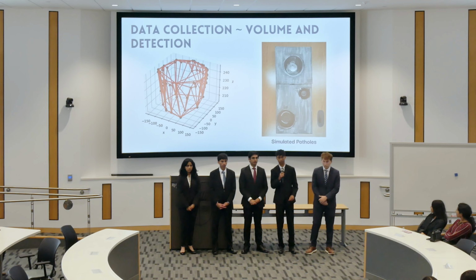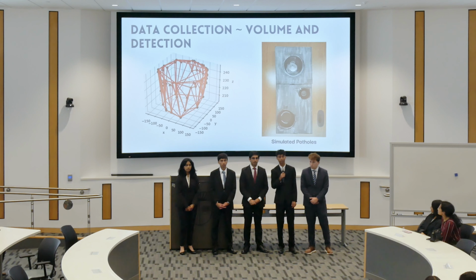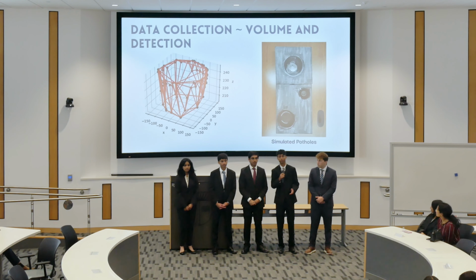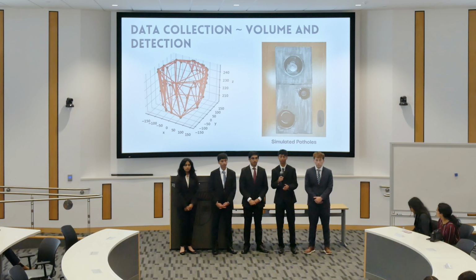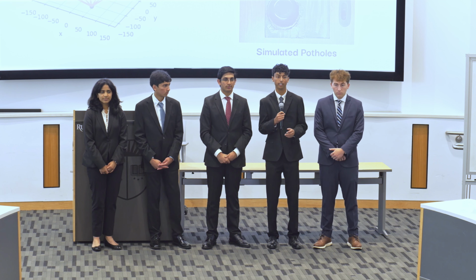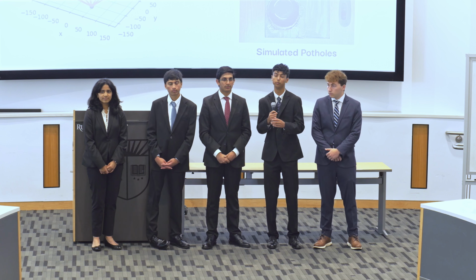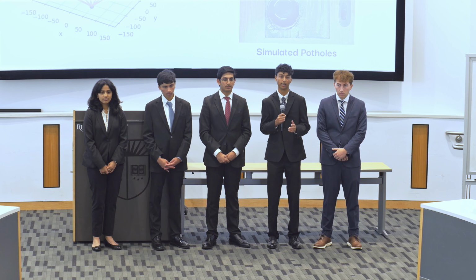For our pothole detection module, we implemented 3 algorithms: adaptive breakpoint detection, iterative endpoint fit, and gradient comparison. Adaptive breakpoint detection organizes our data into curves by identifying corners or vertices. For instance, take a 6-sided dice. This algorithm would partition that die into 6 sections based on the vertices. Next, iterative endpoint fit is applied to simplify our data by approximating these curves with fewer points, allowing us to do real-time detection. Finally, if a significant deviation in slope is observed between these segments, then a pothole is detected.